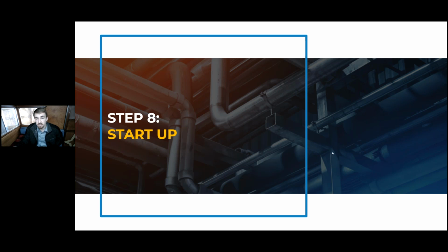Yeah, so at Jackson, we have an electric water heater in parallel with the heat pump water heaters. If you're using a gas water heater, it could be the same way. Oftentimes, I've seen gas water heaters paired with the swing tank, since the swing tank is the last tank that all of this hot water goes through before it serves the building.